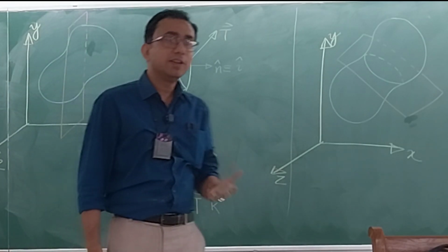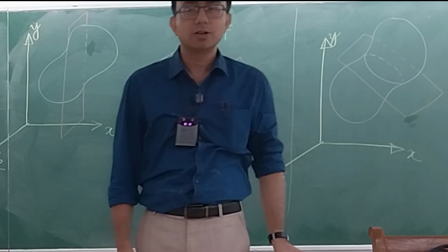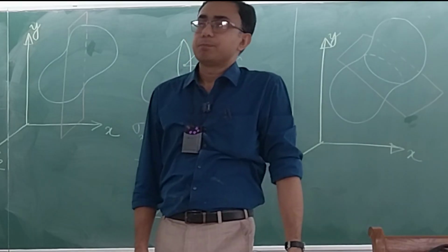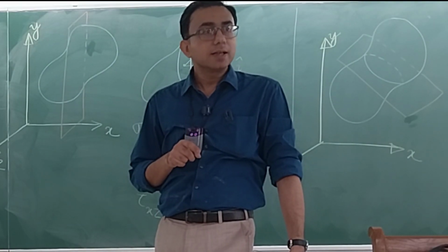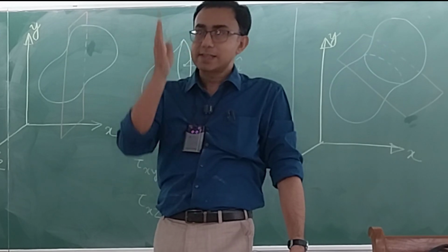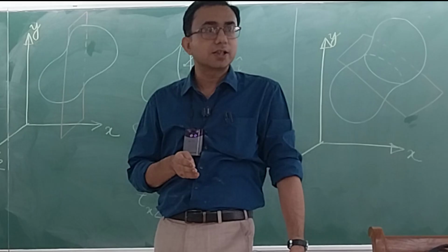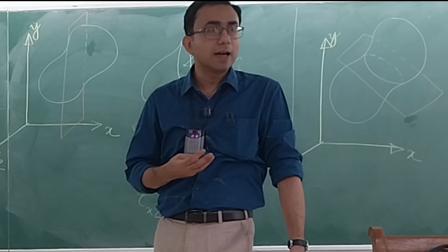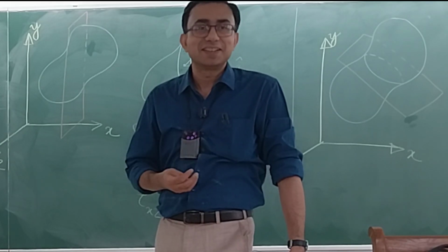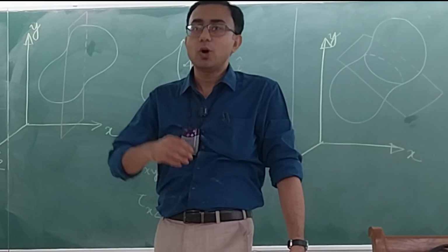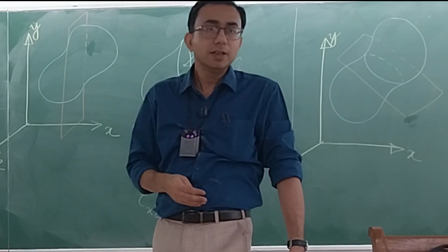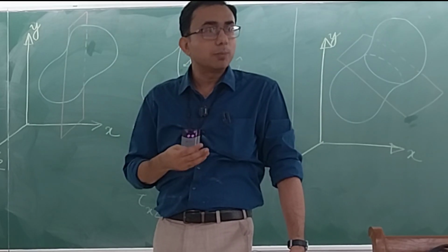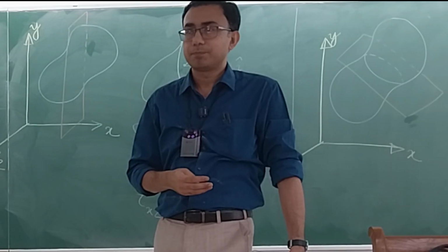Actually, you have encountered this. You didn't recognize this probably. See, when you are doing bending, sigma is equal to minus My by I. On that surface or on the cross section, do you not have different values of the sigma? So all those sigmas, the sigma x, different values, they happen to be the x components of certain traction vectors.